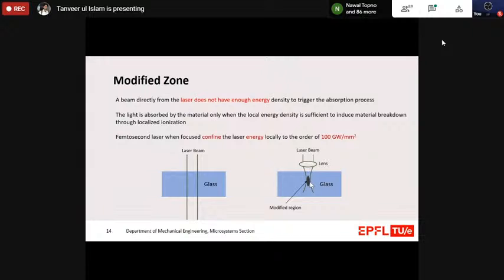However, this is also dependent on the optics that we use along with the laser that is already there with the system. So if we keep on increasing the magnification of the objective that is used to focus the laser beam, we keep on decreasing the spot size, but it cannot go smaller than the wavelength of the laser light that we are using here.